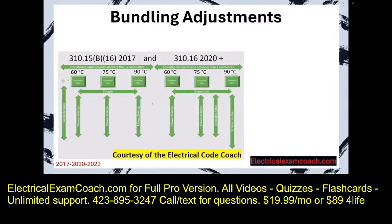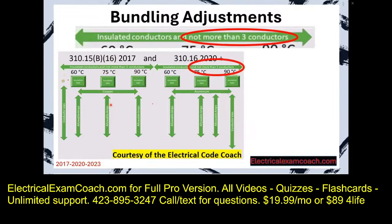Let's take a look at our primary ampacity table. I want you to turn there now. And these values down below this table are true if, well, the question is if what? If you look at the paragraph above the table, the one that I said we would come back and look at later, it's got some parameters there. It says, hey, these are the ampacities of these conductors if, and the first if that we're going to look at is if there are not more than 3 current-carrying conductors inside of a cable, pipe, or even buried in the earth together.